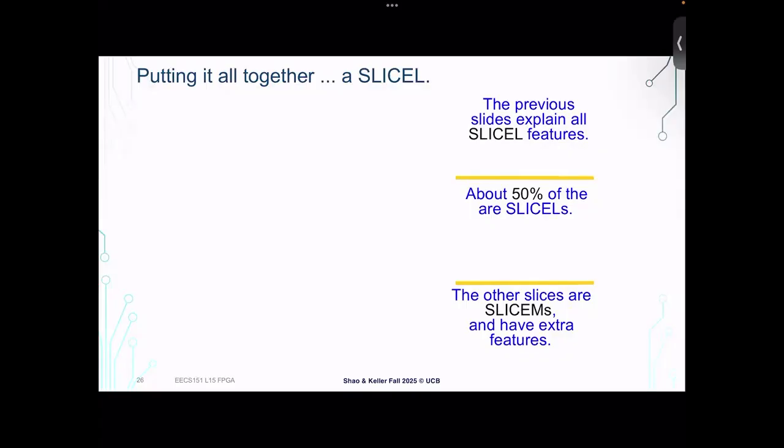Yeah, exactly. So you can either use it as one big 8 LUT, or you can implement 16 parallel functions as the 5 LUTs, right? Or you could have one 7 LUT and eight 5 LUTs. You can do it in many different combinations, allowing it to either be used for a lot of little things or one big thing. That's kind of the way that they decided.